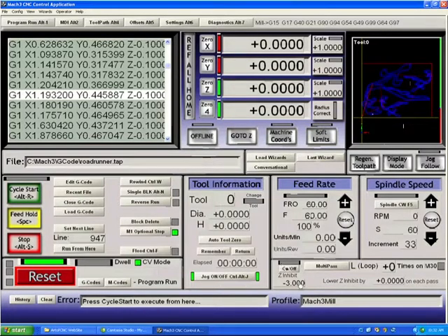This section of the screen here is used for multipass. Again, you don't need to worry about it unless you know how to use it. Generally though, if you have a Gcode file which is set to a particular depth, say it's set to cut to -10, you could hit multipass and tell that file to cut 5 times, dropping 2 each time until it hits 10. So it is literally a multipass selector, allowing you to cut a file in multiple passes.